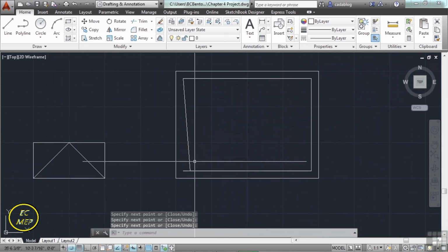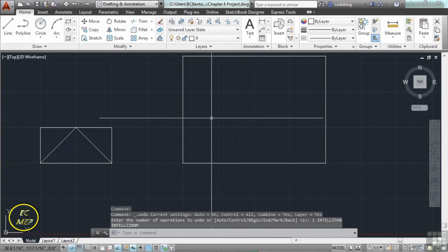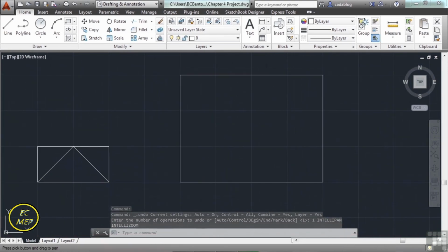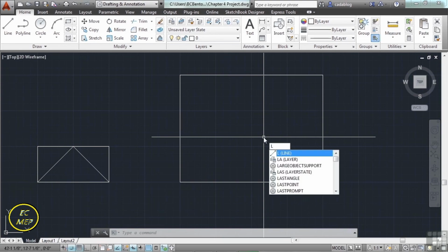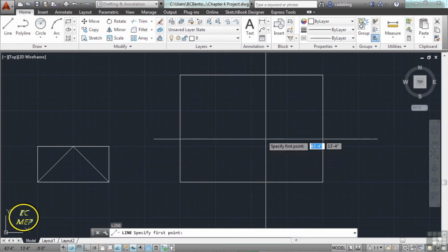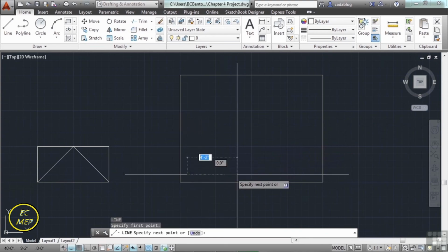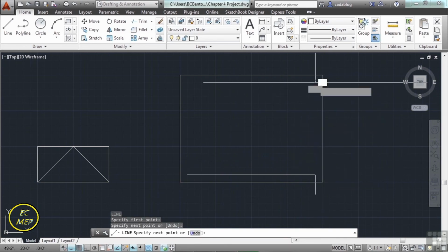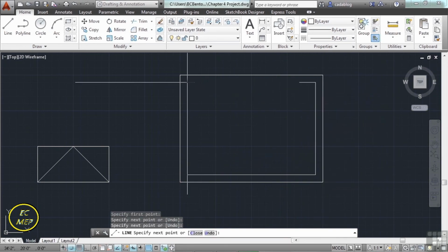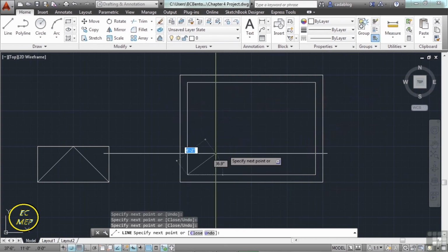Okay, I snapped to the wrong spot here, so let's undo that. Go up to your quick access toolbar and click the undo arrow. Well, it undid my whole inside box. Yes, because we did all of that in one command, in one function. So we need to draw that back. Draw a line, start the line command again. And let's draw. We'll keep the width of this box on the inside of the other box to just 1 grid space wide. When you're done, press enter.